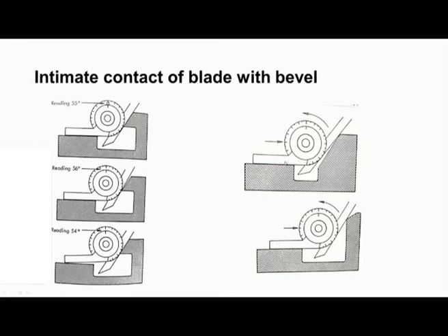So, again see, one blade should come in contact with one surface of the workpiece, and then we should slide the protractor like this till the other blade comes in contact with the beveled surface, and then further we should push the instrument so that there is proper contact at this place. Then we should take the reading. We should clamp the blades, and then we should take it out, and then we can read the instrument.